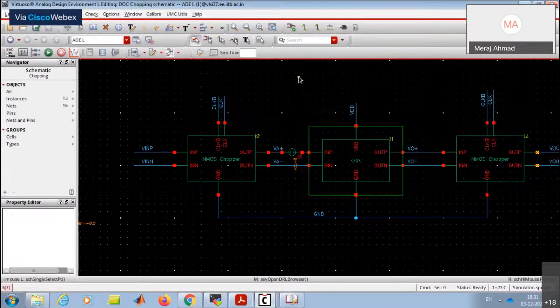If you are talking about some commercial IC, you can use the LMP series IC, 900, I don't remember exactly. They have, I think, bias current in picoamperes. If you are using a commercial IC from TI, they are using the same bias current cancellation in their design.